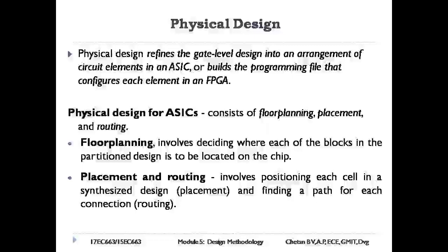Placement and routing. Placement and routing involves positioning each cell in a synthesized design and finding a path for each connection. The main goals are to position all cells and route all connections while minimizing area and delay of critical signals. The result of placement and routing is a suite of files to send to the chip foundry for fabrication.